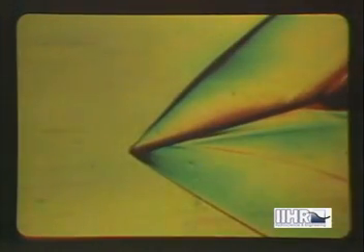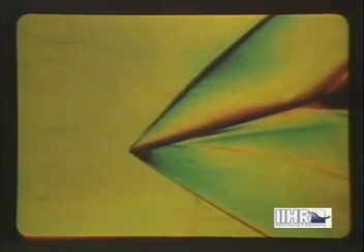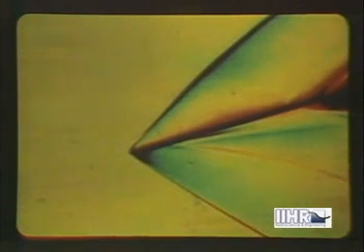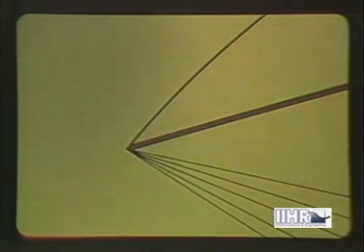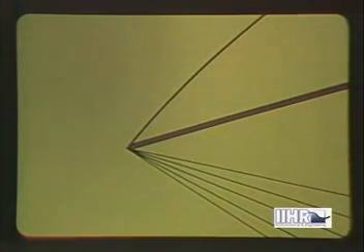Previous scenes of water waves at a change in wall alignment are reproduced in the shock wave that is formed on the upstream side of this inclined plate. On the downstream side, however, there is no shock wave, but a zone of rarefaction, which is represented schematically by a series of divergent negative wavelets. As the streamlines pass through the shock wave, they necessarily come closer together, and the pressure rises. On passing through the divergent wavelets, on the contrary, the streamlines move farther apart, and the pressure drops. Such changes characterize all of the more complex phenomena of supersonic flow.